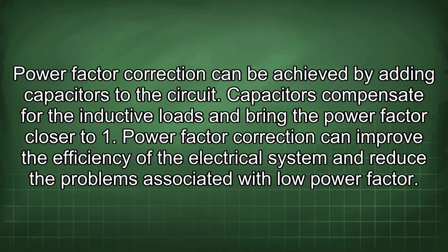Power factor correction can be achieved by adding capacitors to the circuit. Capacitors compensate for the inductive loads and bring the power factor closer to 1. Power factor correction can improve the efficiency of the electrical system and reduce the problems associated with low power factor.